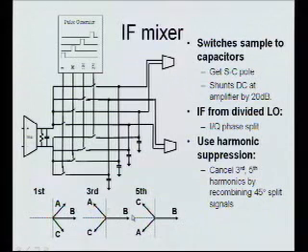That's no good. So if I were just generating signals and adding them up, this would work. But it turns out this also works if I take a signal, multiply it by these 3 signals, and then add them up. The phase still cancels. I mean, there's no easy way to convince you of that except to try it out. It's actually a pretty straightforward thing. But in effect, what it does is it means that you've nulled out the third harmonic mixing term and the fifth harmonic mixing term, but you're still keeping the fundamental mixing term strong.